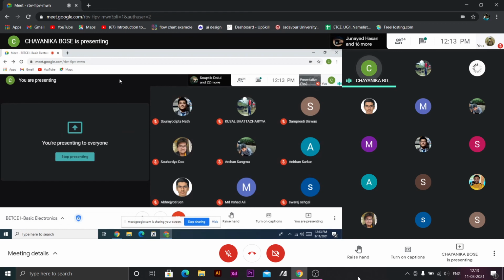Now if you tell that our VC is 0, that means the collector base junction is under full forward bias, because the collector base and emitter base are two diodes connected back to back, if you think like that. So the base emitter junction gets 0.7. So when the collector base junction also gets 0.7, then full forward bias, then the external voltage will be 0.